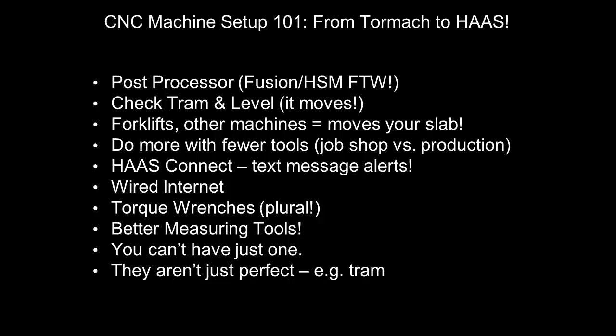I have learned the hard way that you need to be using torque wrenches. We actually had some jaw lift on our orange vices, which I was blown away by because those are really high quality and expensive vices, and I was pretty upset for about a day. And then I realized it's my fault. You have to take those half 13 cap screws to 65 foot-pounds, which I was not doing, and your problem is solved.